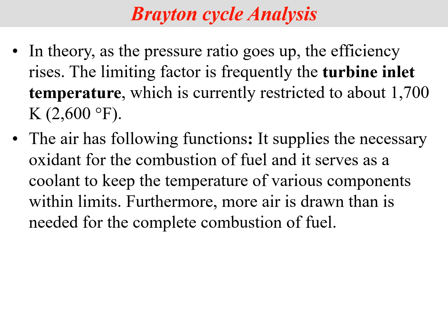So one of the limitations in designing a gas turbine is, first of all, the temperature. Why are we restricted to about 1700 Kelvin? The very obvious answer is material constraints. We can't construct turbines out of, what do we say, tungsten or something.